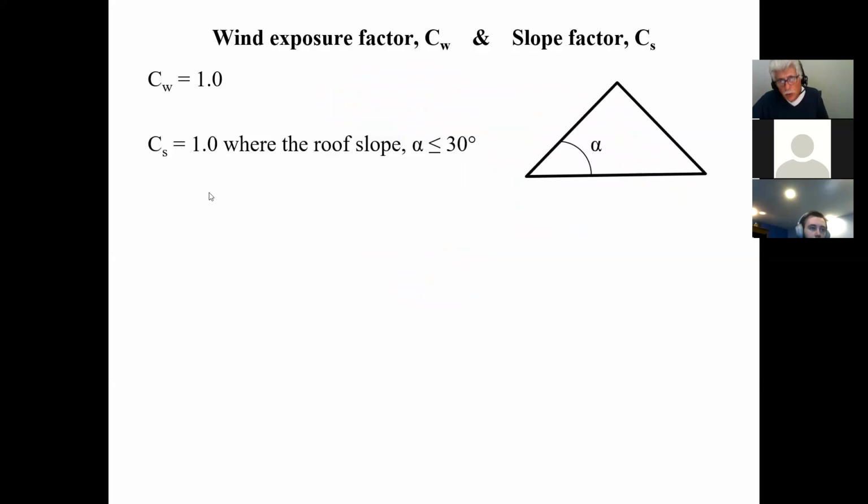Now, this I do use because I know that if I put a slope on my roof, it's going to stay like that unless the roof collapses. That means I've underestimated my loads. Or people have let the snow accumulate beyond the design load, and they're stupid because they don't realize that every roof has a certain limit. And when you get up to about 4 feet of snow, you should go up there, even though it's been designed for 4 feet of snow, to remove the snow.